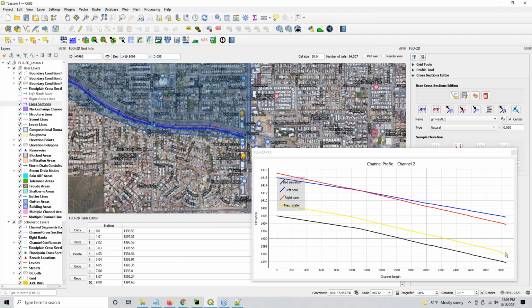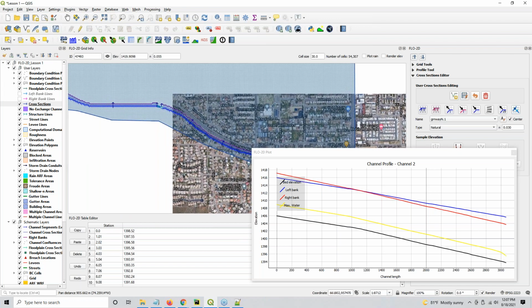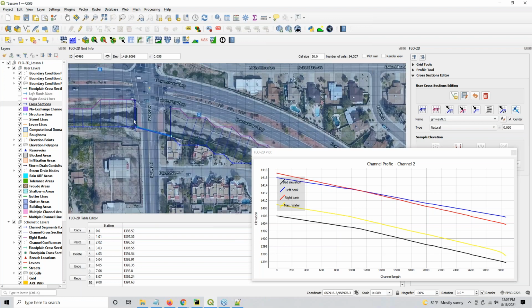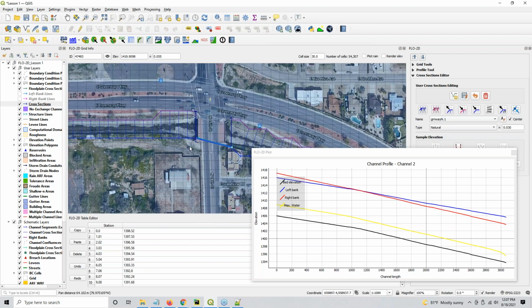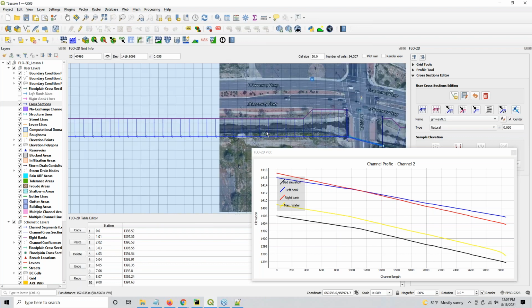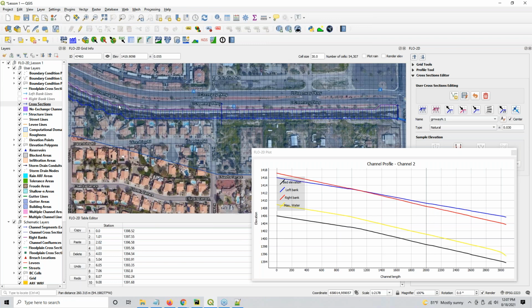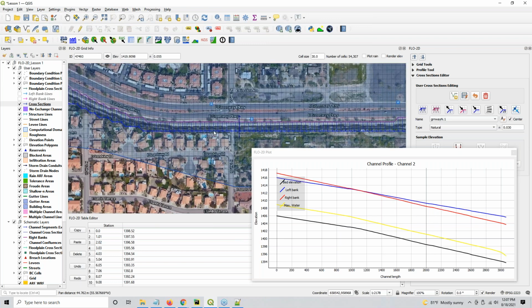But that structure might actually do that because it's a huge structure and there is a bit of a drop on the downstream side of it. So it might actually draw that water surface down from this point right here. That might be okay. And since I didn't have any other issues with my channel, it looked really smooth and I didn't have any instabilities, I think I would trust it.